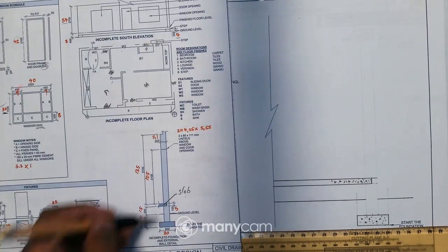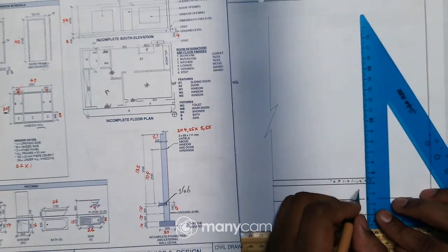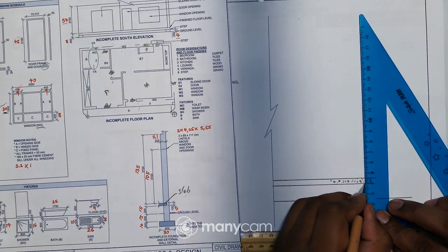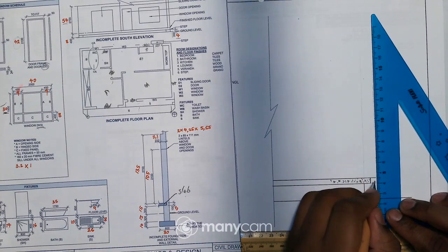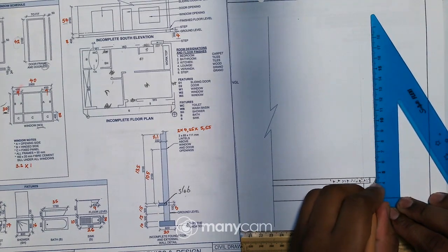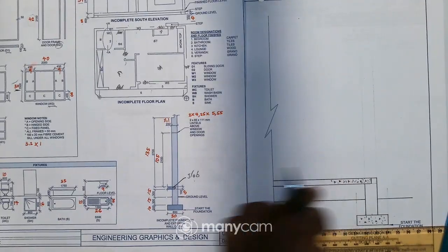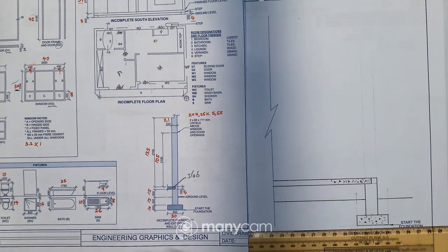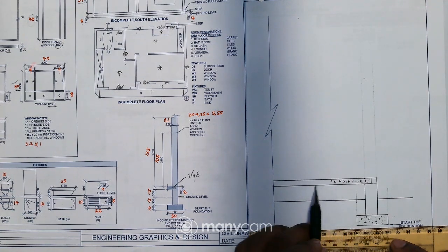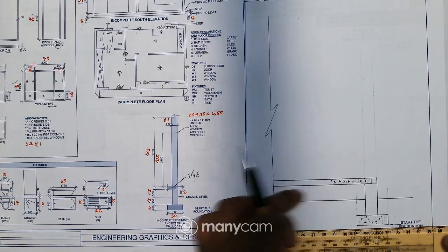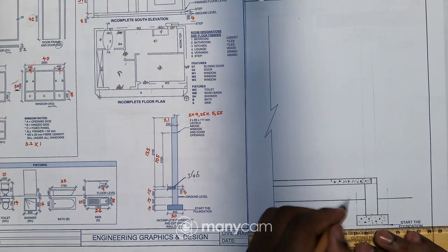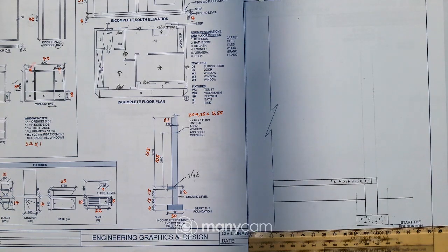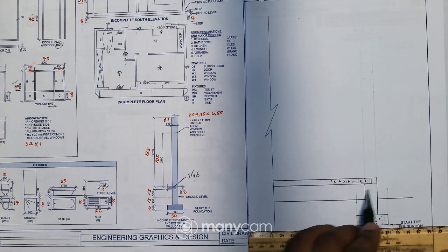Okay, and then from here I can just draw this wall here, right, and also there, because I want to hatch this section. So this section is the hardcore filling, the compacted sand, because before they put this concrete they have to compact inside around the building, right, before they pour the concrete.